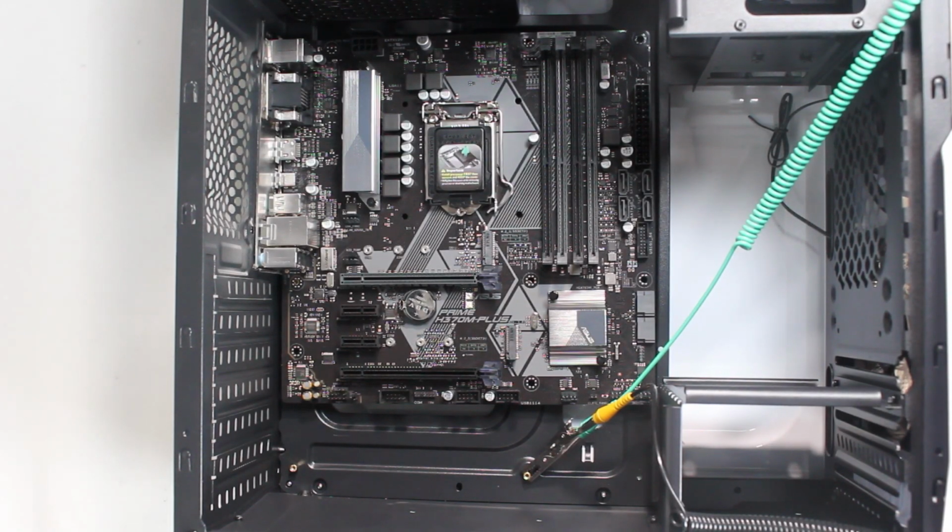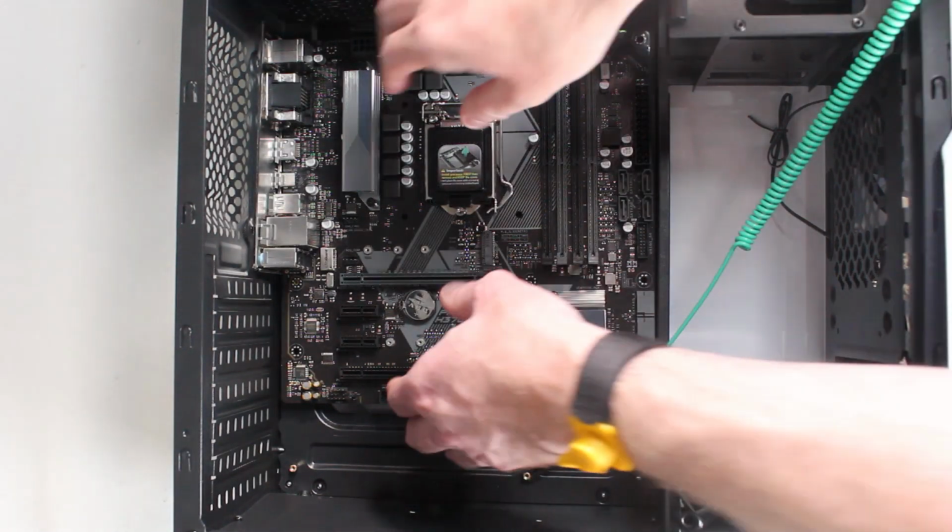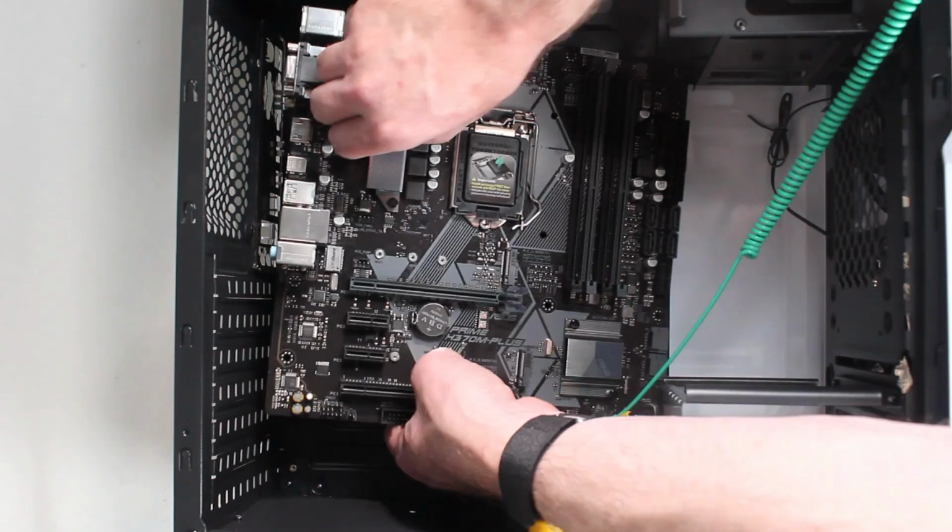We can use 4 of the existing standoffs and 2 we cannot. If the additional standoffs are in contact with the motherboard, they need to be removed. In this case, the 2 extra standoffs are not touching the motherboard, so they can stay where they are. So, another 4 standoffs will need to be installed for this motherboard. The next step is to remove the motherboard and install the additional standoffs.